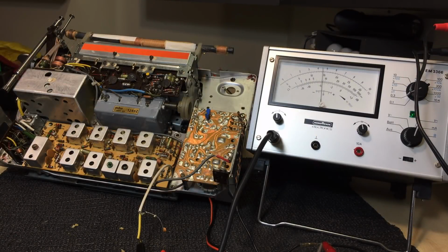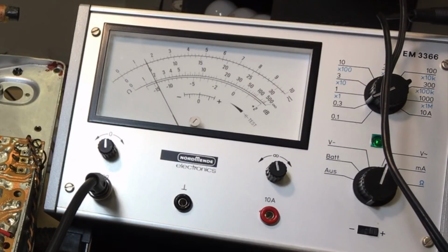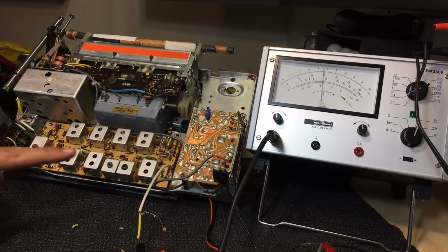Okay, I've made a discovery here. I had it peaked at 455, as you recall, and then I went to the signal generator and I put it at 456 and it went down, which is great. 457, 58, that's expected. Now, 455 is there, 454 went crazy, 453 went crazier, 452 jumps down. In other words, this thing is actually tuned to 453. And that means those two in the middle need adjusting as well.